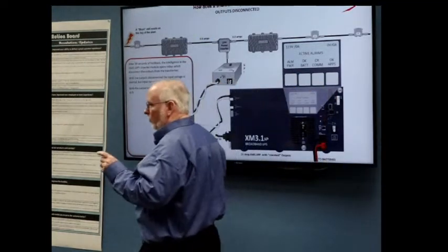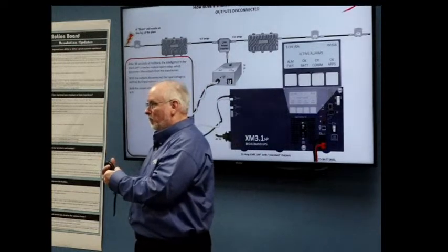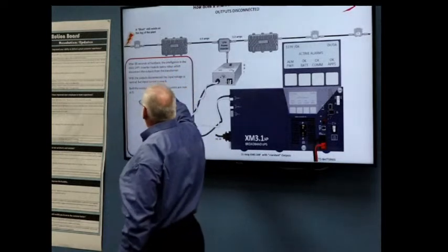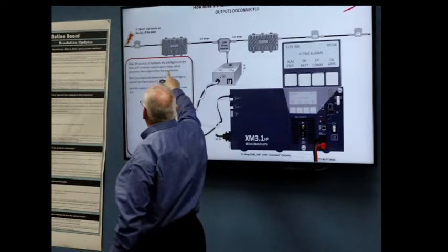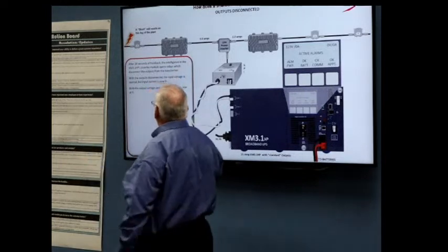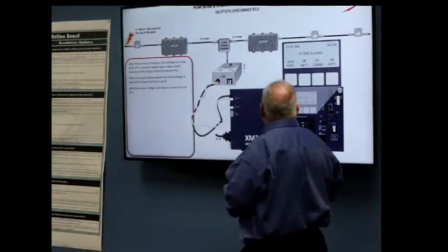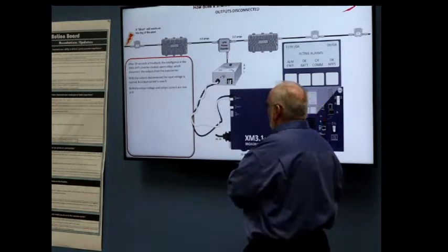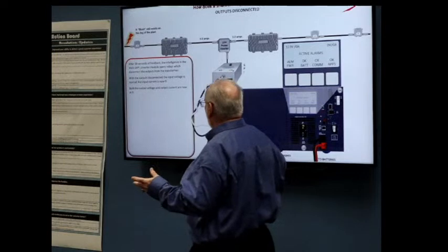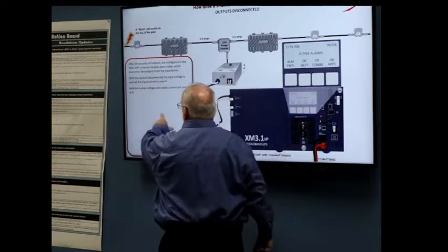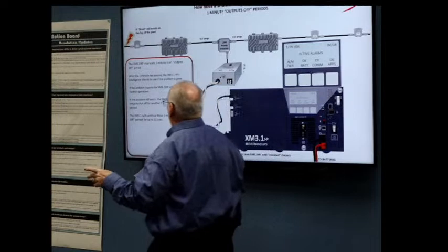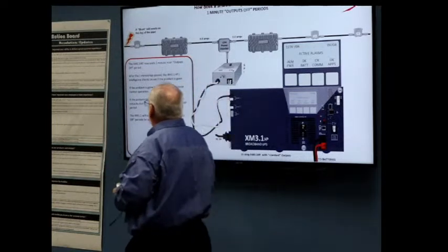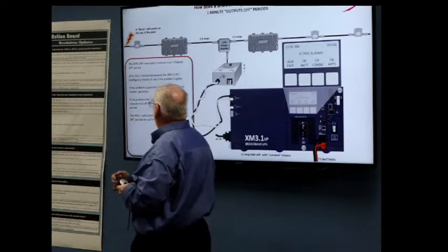After 30 seconds of foldback, so effectively a short, right? The power supply for 30 seconds will do its best to deliver. Then it's going to intelligently switch the HP inverter to open, which will disconnect the units from the transformer. So no draw, no output voltage, no output current. For all practical purposes, it shuts itself off. Now it'll wait 1 minute, right? That's the reason I have to read this, because it's very timing centric. 30 seconds on, now it's off for a minute.